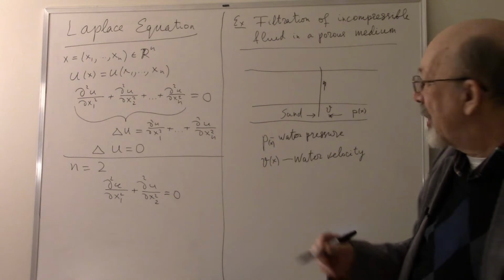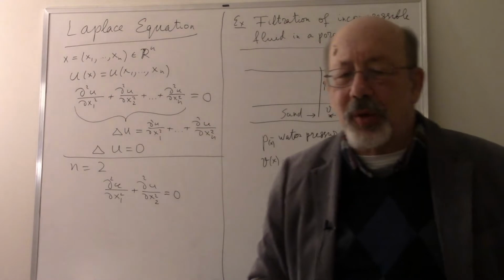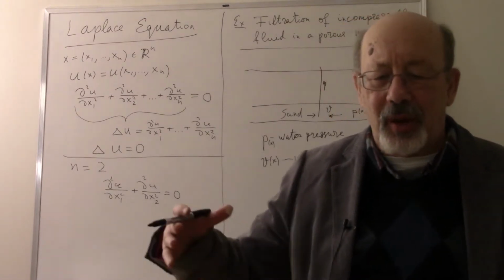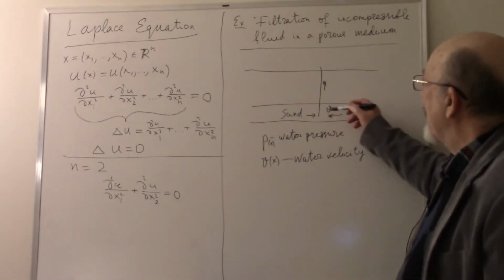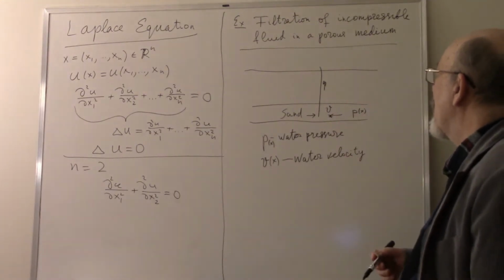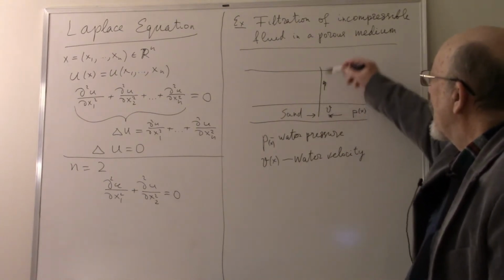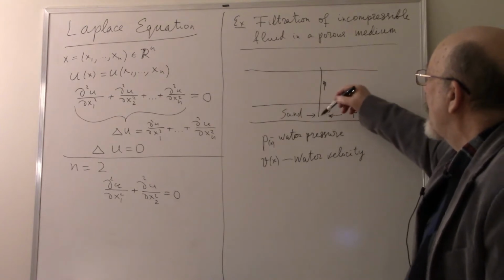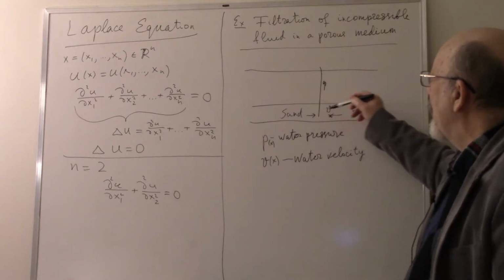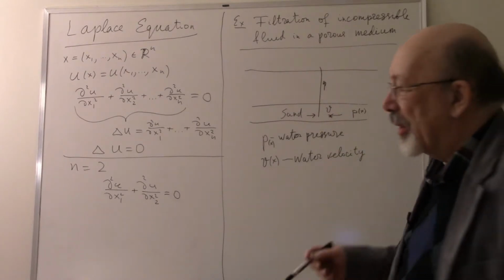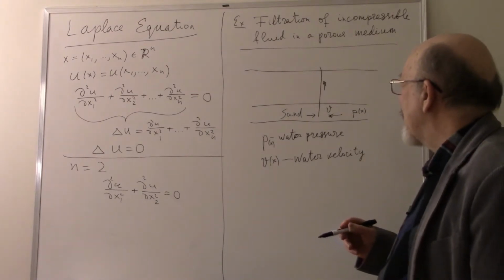Now, in practice, if you are not very close to the well, the velocity is small, but nonetheless it is enough to fill the space which was previously occupied by this water. Now some volume of water is pumped up, so the water from the side comes and replaces it. So this velocity is maybe small, but not zero.